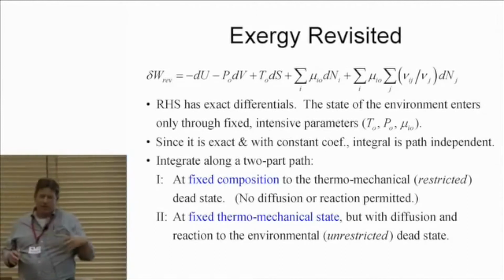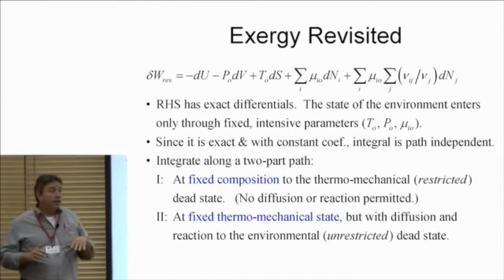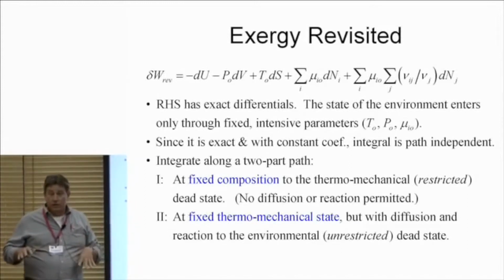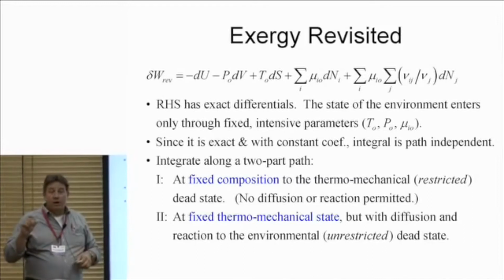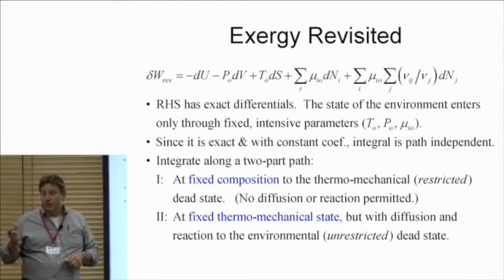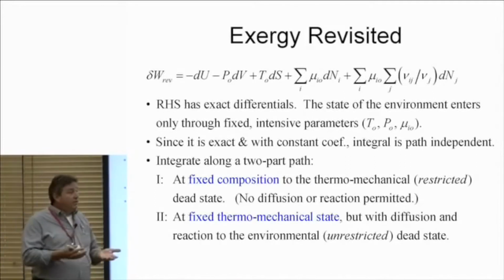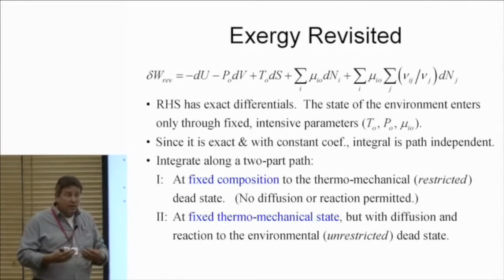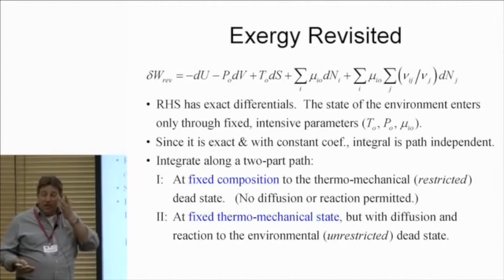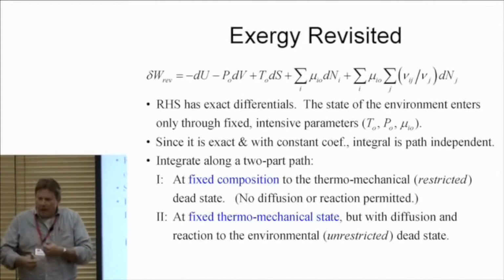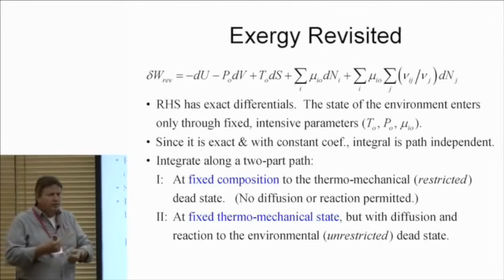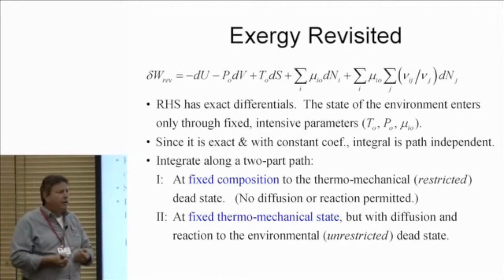So this is an important thing in thermo. I don't know if you remember this or not, but exact and inexact differentials. The little squiggly d's, the delta N's and the rest, those are amounts. Those are inexact transfers, and I have to have a prescribed path to integrate those functions. So work is something that you do, not something that you have. We never talk about a change in work. We talk about how much work you do, and I would have to integrate along a path of doing work to figure out the total amount for that.